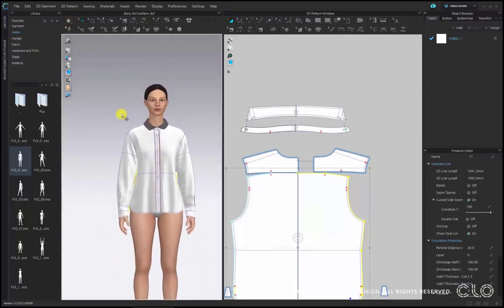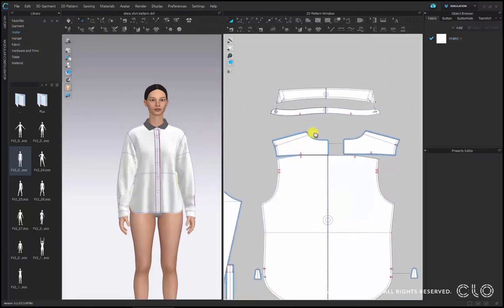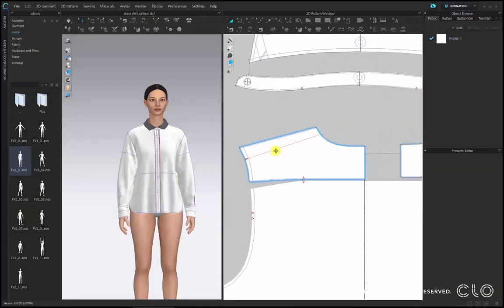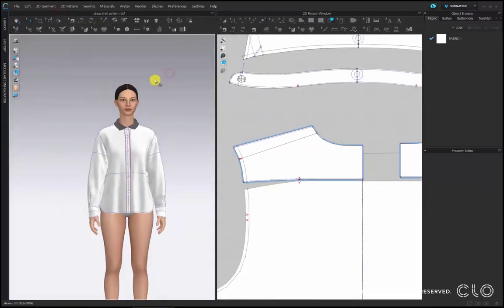Now I'm going to align the shoulder position of this shirt according to the back panel of my back yoke pattern. You can see the shoulder position here marked as a baseline, according also to the notch on the outside. I use the trace tool, shortcut I, press enter to transfer it into an internal line so I can use it. Then I press 5 on my keyboard so I get the bird view on my avatar.